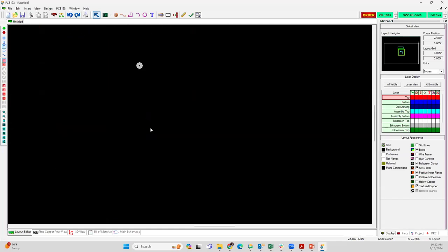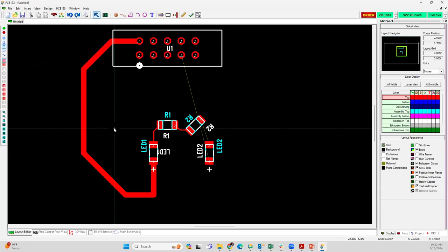It is a good way to figure out if you've got enough room on your board to actually route everything. So sometimes I'll have a board and I'll wonder, gee, will I have the ability to wire this up? Is there enough room on the board to do it? So I auto route the whole board just right after I finish placing my parts, and if it gets close, I'll know that there's enough room for me to go back, delete all of the auto route stuff, and finish hooking up, or route the board manually.